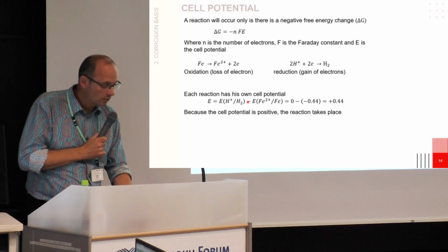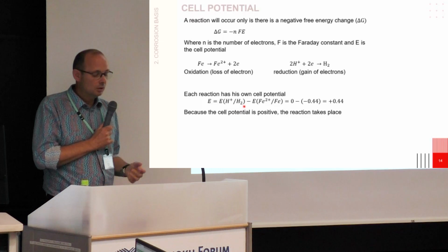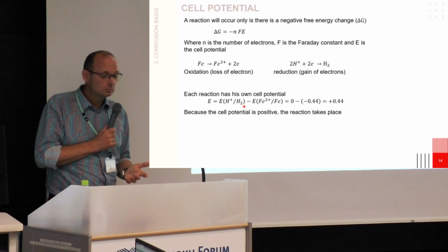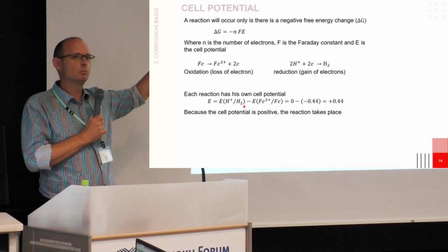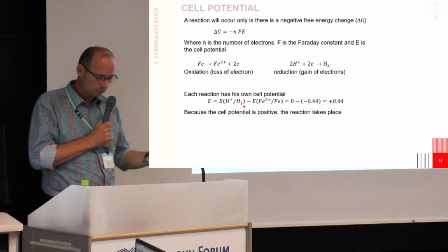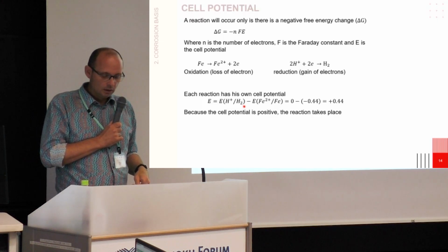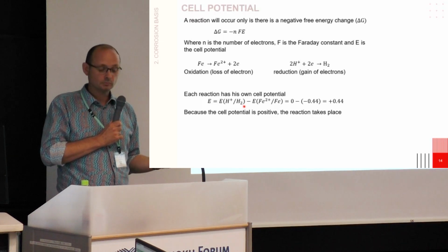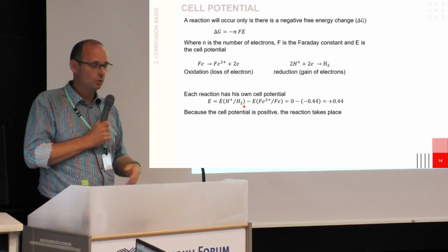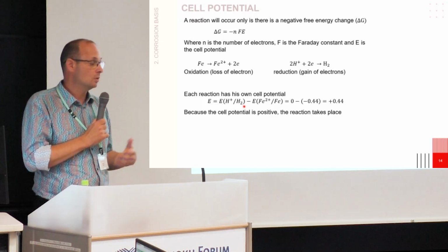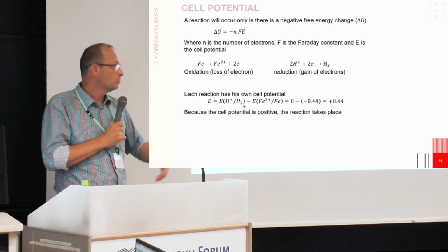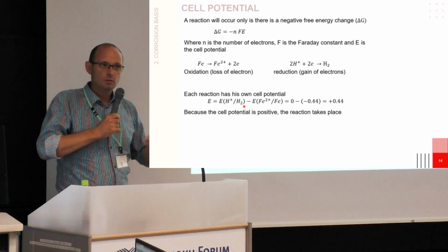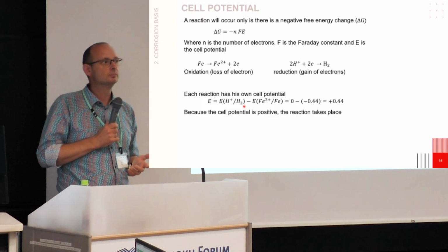For example, in this case, we are looking at the dissolution of iron in acidic environment. It was mostly my first example. So if you look at the thermodynamical data, you will see that you have a cell, because you are doing a difference of potential, and it is 0.4. This is positive, the value is not negligible, so the reaction can happen. Okay?